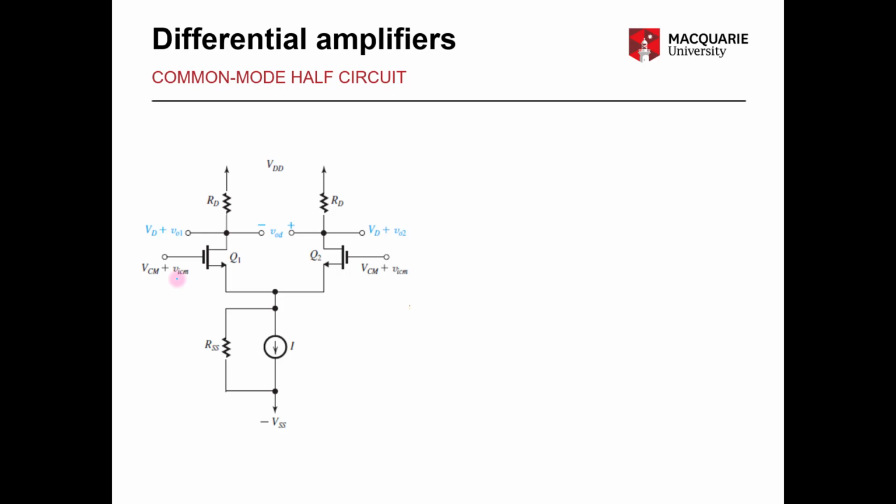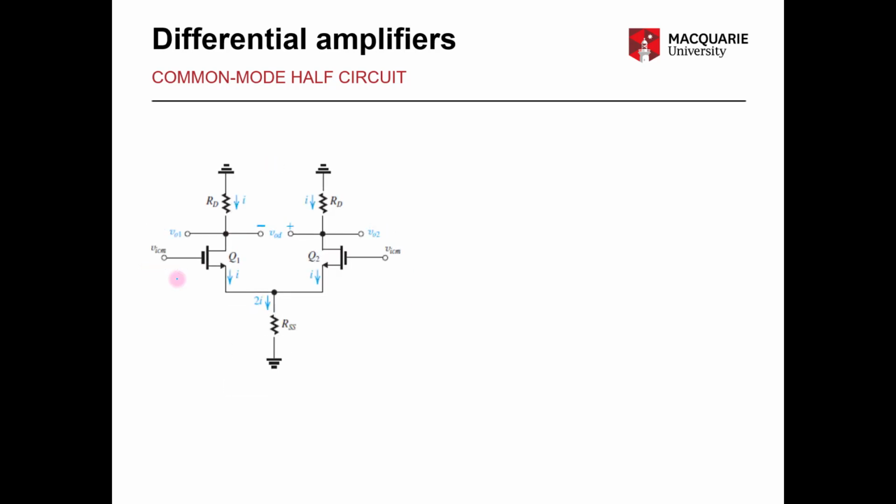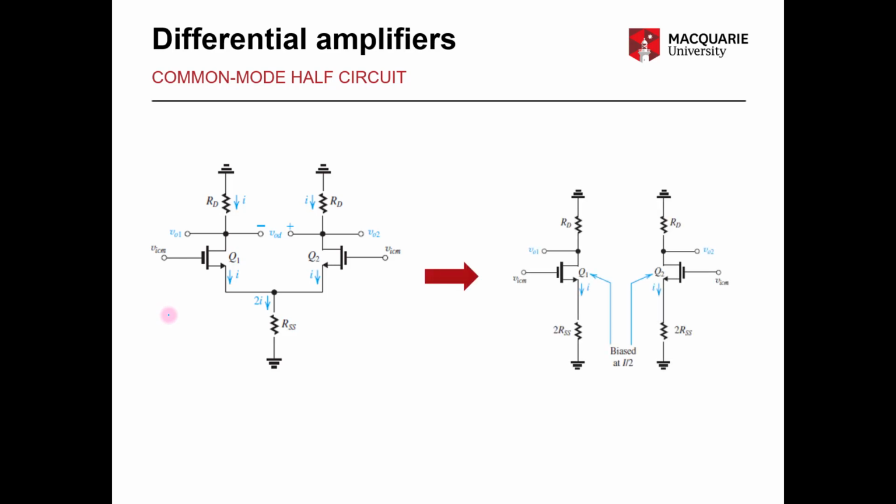So in this case, the first step would be to switch our circuit to a small signal model. So here we have removed the current source and set the power supplies to ground. This immediately simplifies our analysis, and this is the state set up by our large signal VCM.